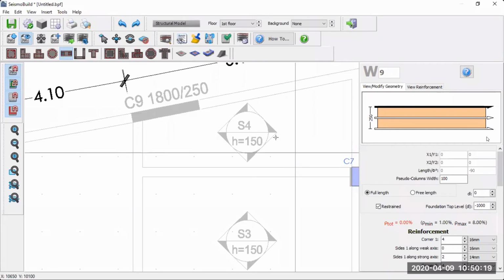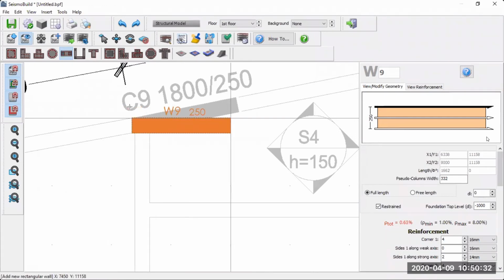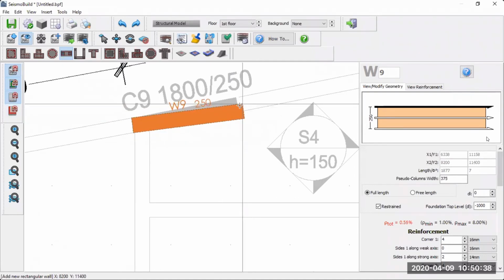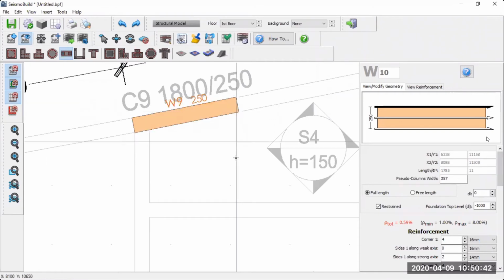All right. So you select whichever line you want, and for instance, I select the top line. So I will move here. From here, I will click my wall. Because you notice that I already have snap to auto on, I switch it off. Then it will follow the line here. So we can select the next line. You click. This is how you insert the wall. It's very simple.